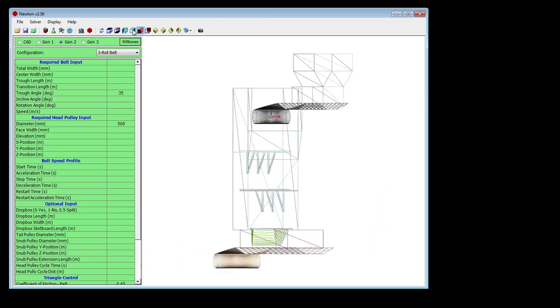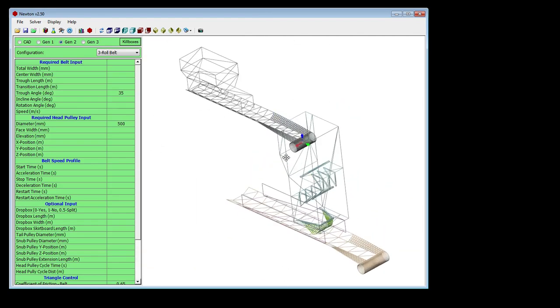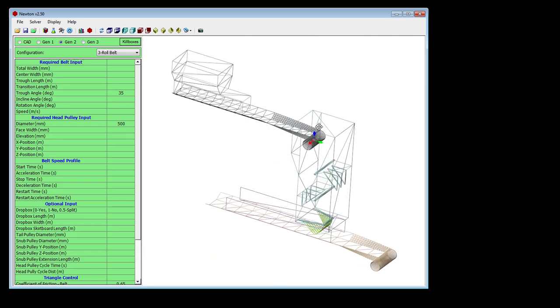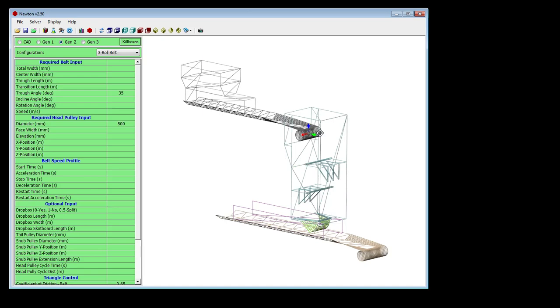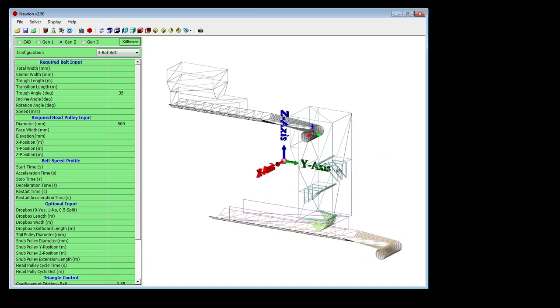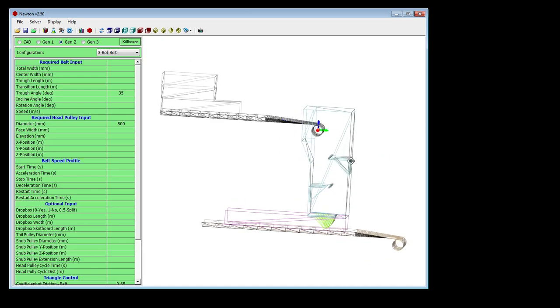So one of the advantages of STL files is that it's supported by basically every CAD type, because the STL type is what you use for 3D printers, so pretty much every CAD program is going to support it. So it's kind of like a last resort. If you can't export to IGES or step files, you can always use the STL file type.